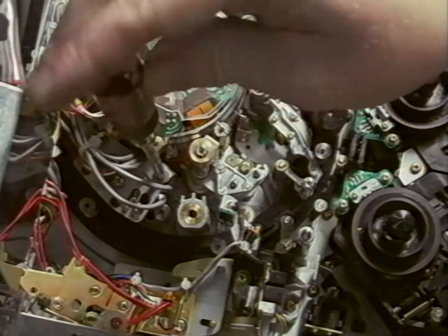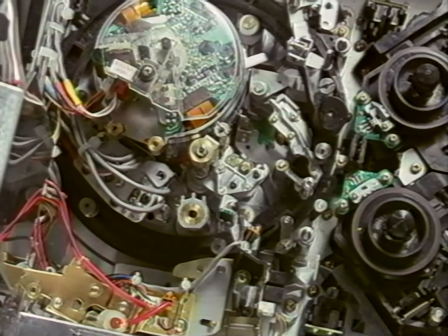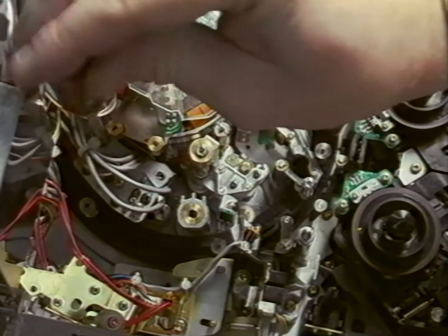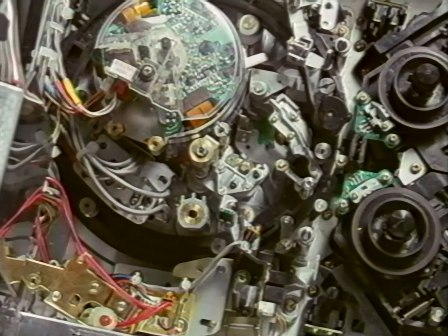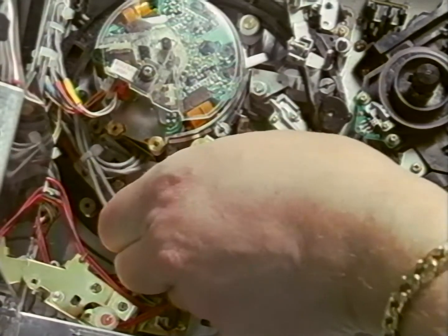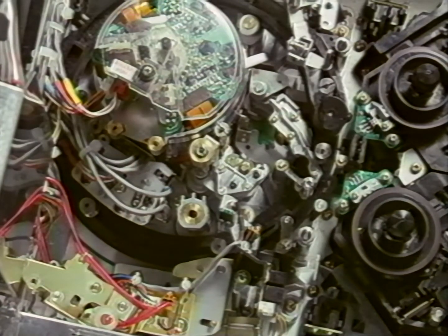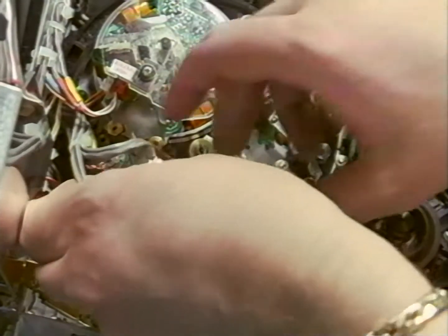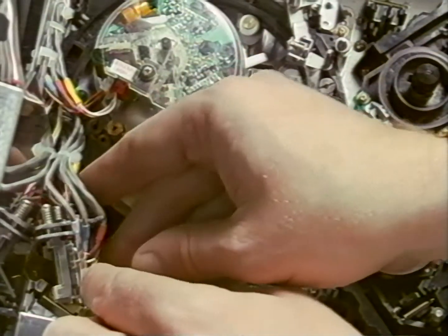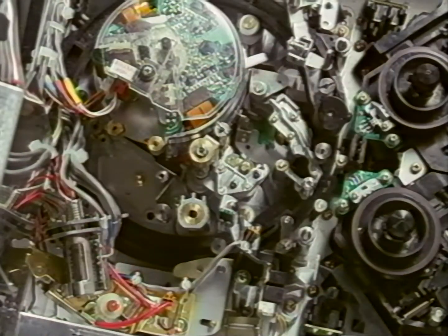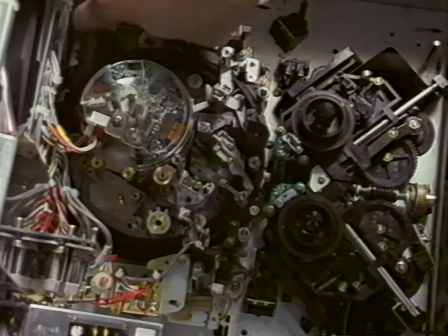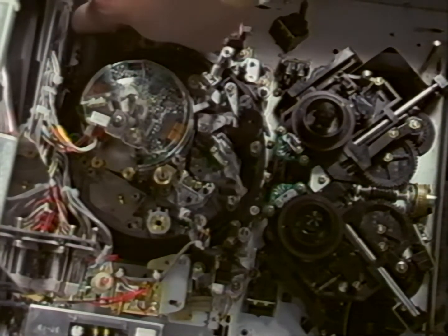Remove the pinch retainer, the full erase head block, the pinch solenoid block, the ring sensor block, and the audio time code block. Turn the gearbox pulley until the pinch roller is located in front of the audio time code block assembly.